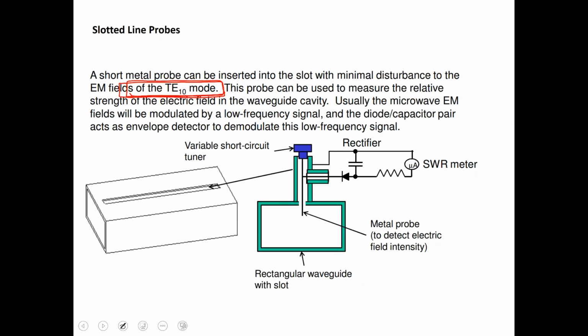So this distribution of the TE mode allows us to create slots within the waveguide. Next week onwards, we're going to do some microwave resonators, in which the side walls are also going to be enclosed with a conductor, and you create another confinement in the z direction, so the field is bouncing back and forth.